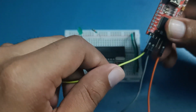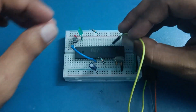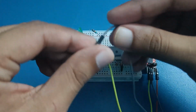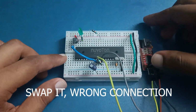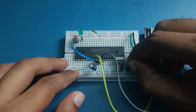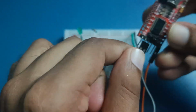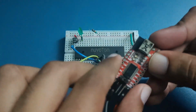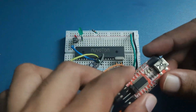This one is the RX, which will go to the TX like this, beside the reset, and TX will go to RX. This is ground, which will go to the ground. This is not giving power to this board. That's why we are connecting only the ground as common. This is just to upload the program. It will connect to the computer, but it will not draw power from the COM port.